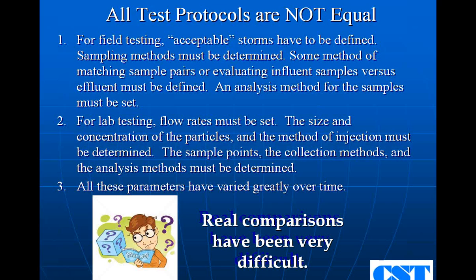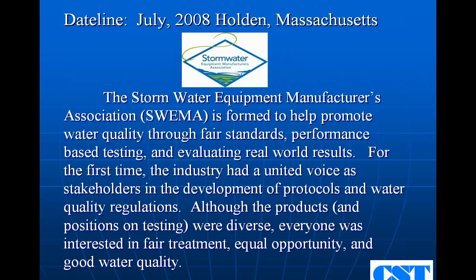And then the sample points. Where do you sample? Do you sample one pipe diameter from the entrance to the device to get influent, or how many pipe diameters below the injection point? A lot of things. So how you collect it, and then how do you analyze it? All these parameters vary greatly over time, and a real comparison of testing has been very difficult.